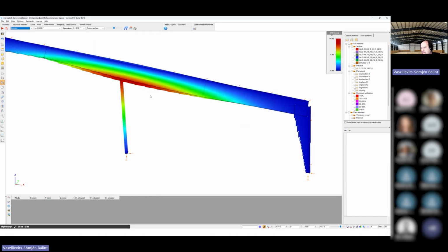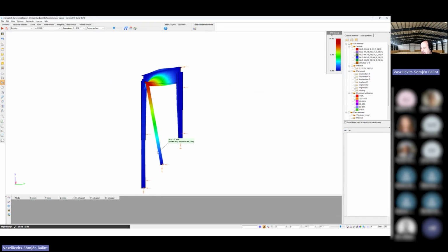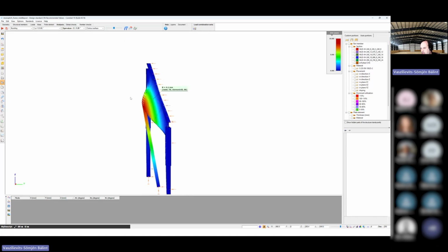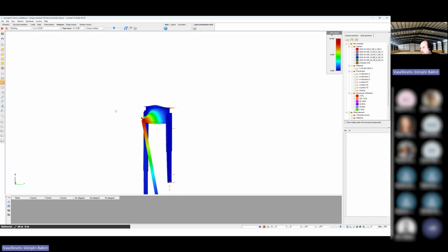Then what we can see now is that this column is moving as a rigid body. It's a sway-like deformation. It's not bending, it's straight. And what happens is that it completely kills my rafter. I have here a hinged connection. This is acting not at the center of rotation, the shear center, but eccentric to that with a hinge connection. That means that this is a destabilizing effect without any stiffness to stabilize. And that immediately causes a very strong torsion to the rafter.